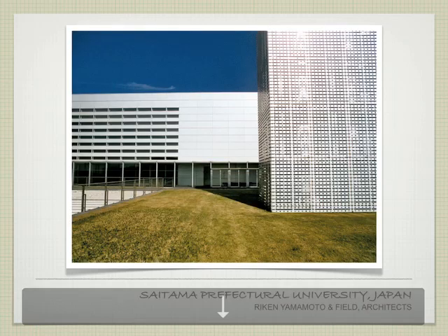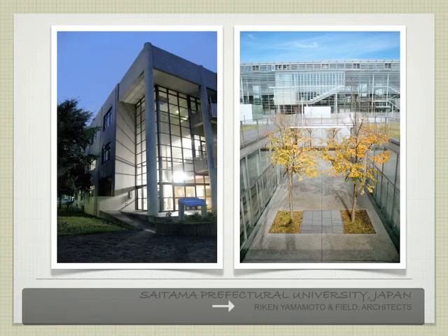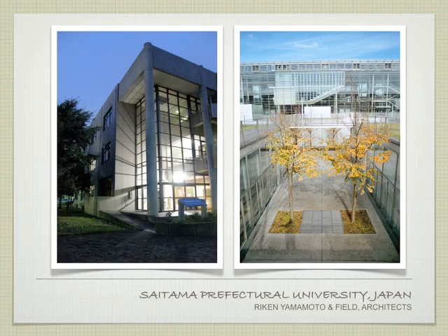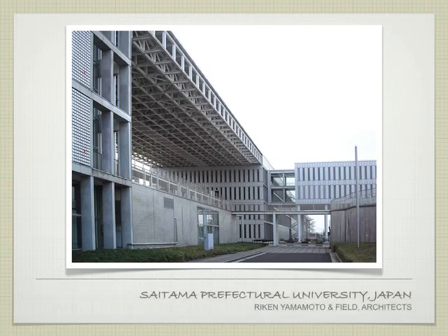And so these are a variety of examples that show you what the university looks like. Each of these is a precast element. That's a column that's been precast. If we look here, there's a beam that's been precast. The stairs were precast. All these pieces came together from off-site. If we look here, another good example, this shows us formwork, so we know that was site cast. There's our little formwork pattern. But if we look at all these elements, those are precast beams. These are precast columns that are put together.